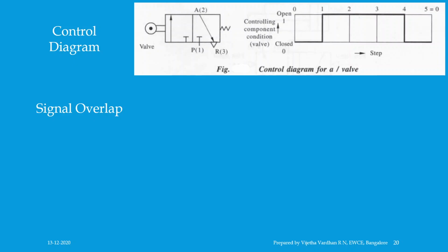Example, signals from limit switches and manual controls which are still operated when an opposing signal occurs, and they do not permit this opposing signal to be effective. Signal overlapping will not take place provided the two signals are of different intensities, and the signal of higher intensity predominates; the lower intensity signal becomes inoperative or insignificant.